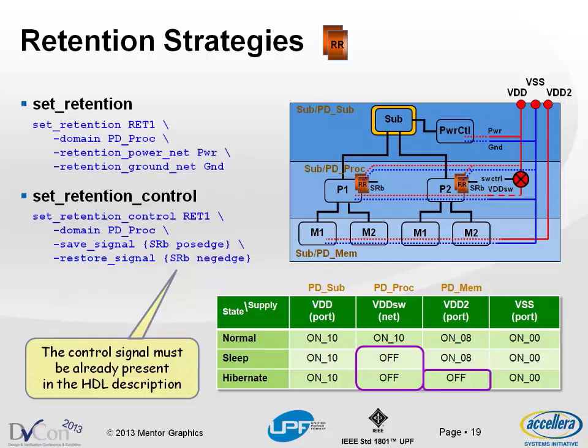Now, there are other places where some power domain is off. Do we have to put state retention everywhere? No, it's up to you. It's your decision whether you want to reinitialize or reset everything every time you come up, or whether you want to retain state, do partial state retention and a mix of state retention and restoration. It's really up to you. This is part of the design process for designing the power intent.